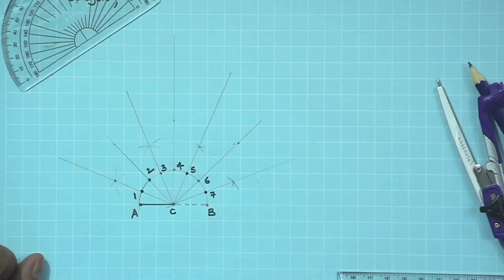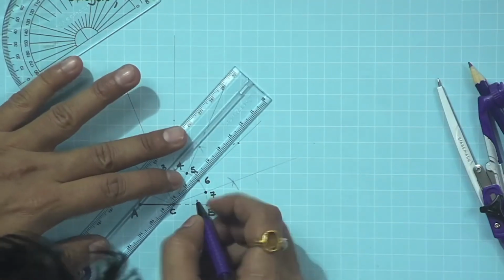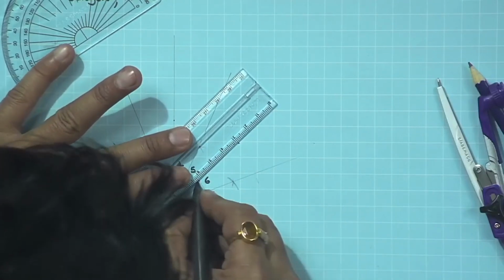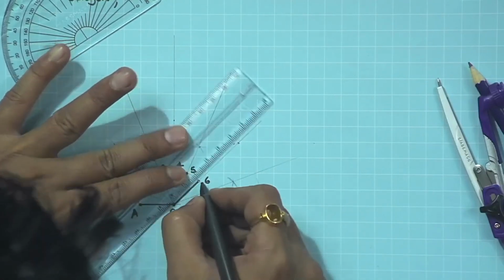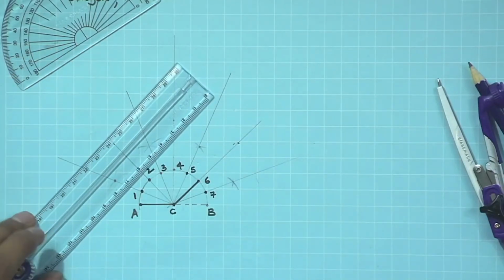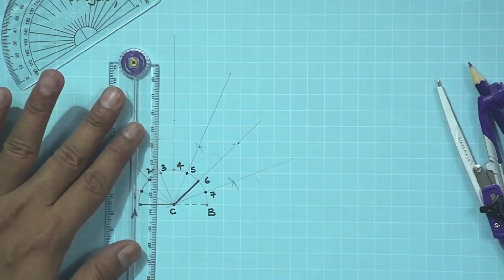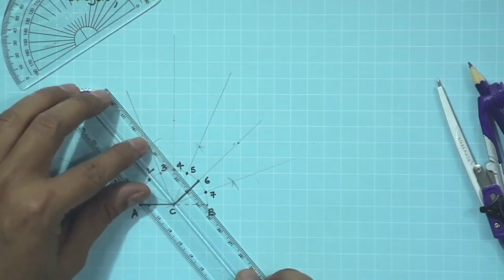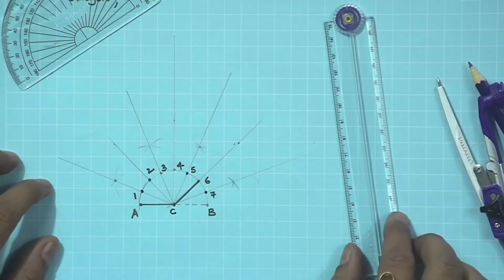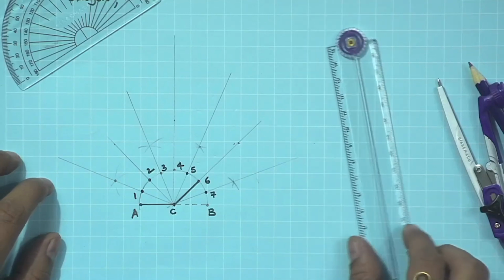Once we divide this into equal parts, connect C and 6th point. This is the point what we have to connect. Draw perpendicular bisectors to AC. So, for AC we have to locate perpendicular bisector and also C6 perpendicular bisector. So, that outside kind of circle we will be in a position to connect, and from there it is quite easy for us to construct the octagon.